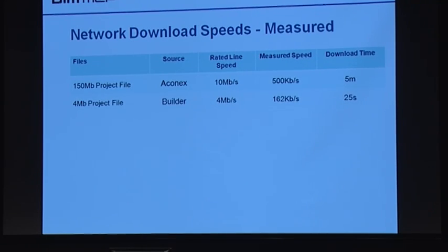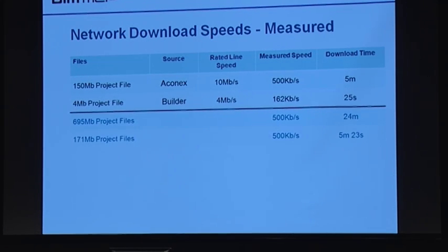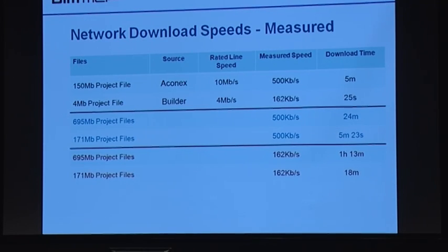We actually did a couple of tests, one up onto AConneX and one off a builder's site. I'm not sure where they had it housed, but they gave me the times of upload speed. We did it a couple of times to test it was right. And so that translates into, in the case of moving the 24 megabytes at 500 kilobits a second, half a megabit a second, 24 minutes to move the files or 5 minutes to move the files. And if I'm at the slower speed, I'm out to an hour and a quarter to move those large files. So if you're hitting the deadline and they say they want them loaded up by 5 o'clock, plan.